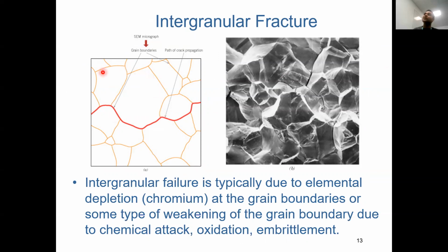So this is one crystal structure. This is one crystal. Now, this is one grain. It will push all the impurities towards the grain boundary. What will actually happen is the grain boundaries will have all the impurities. When something has all the impurities, that will become a weak region. And this is where it will fail. It's not very obvious, but let me draw that one. You can see here, these are grain boundary failures. It just kind of failed at the grain boundaries.